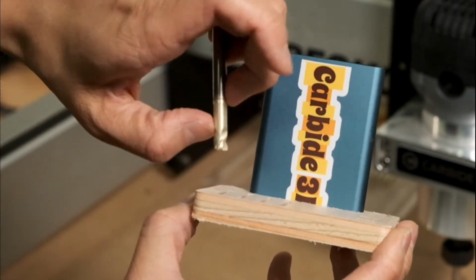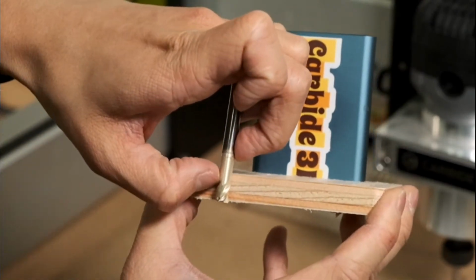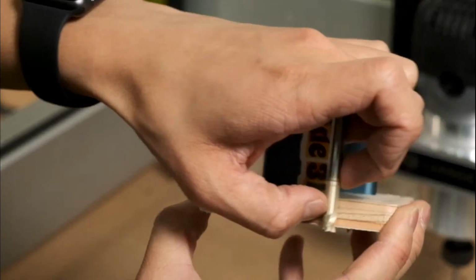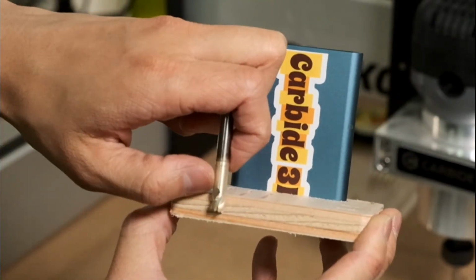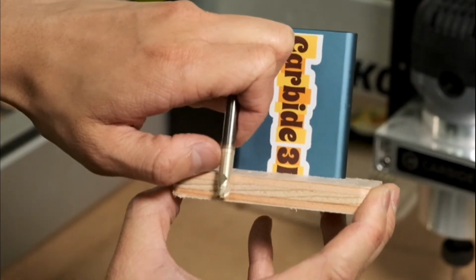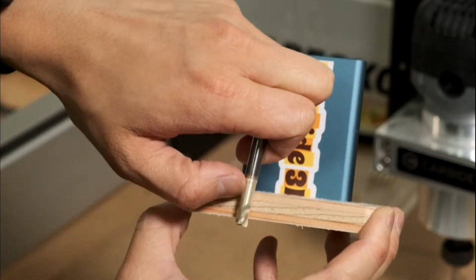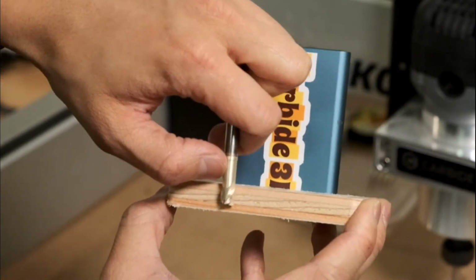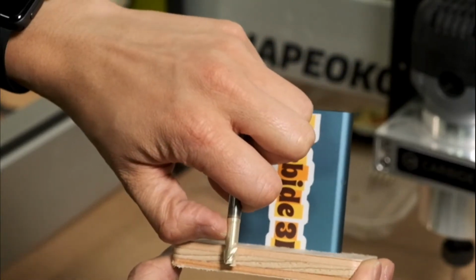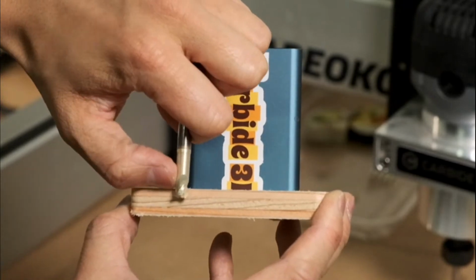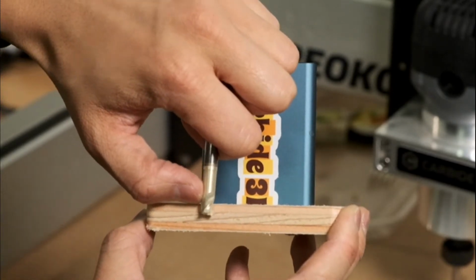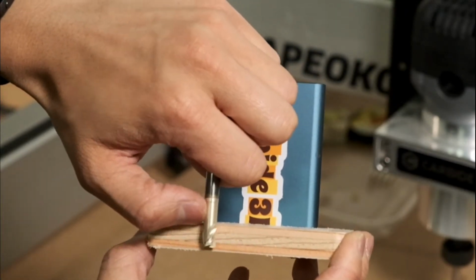And if you don't force past that point on your first pass, the top edge is just going to get ripped out. It's not going to have any of the benefits of the down-cutting portion of that end mill. So if you're confident in your speeds and feeds, you can use it, but it's a lot less forgiving because you have to plunge at least like 1/8 of an inch before those down-cutting flutes kick in.